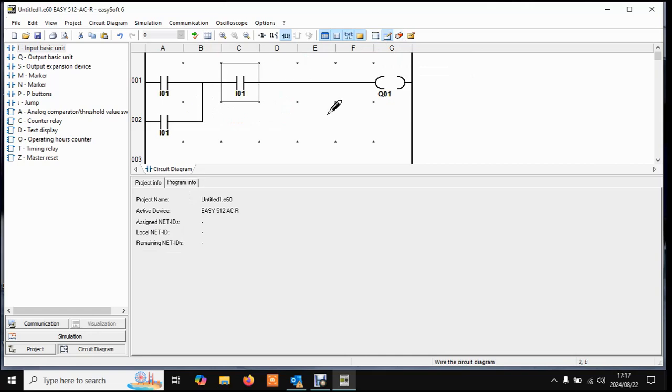Now you can number these switches. So that switch is numbered number 1. This switch is also number 1, so that's going to be confusion. We'll have to rename that switch, because this one will start it. This switch called number 1 will start it. This switch will have to be the stop button. This will be our switch that's in the contactor.